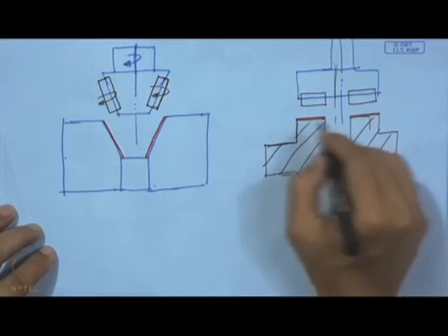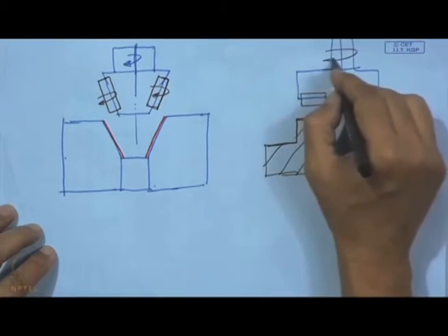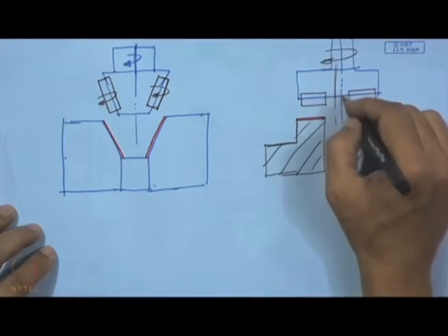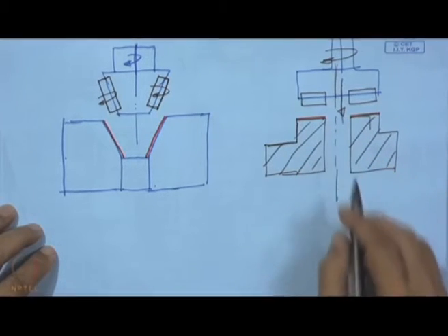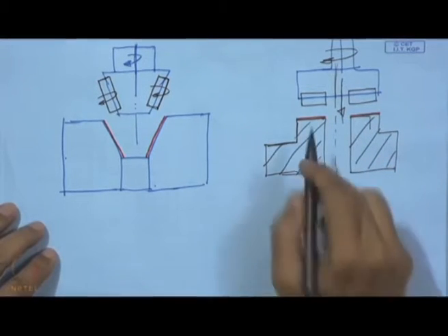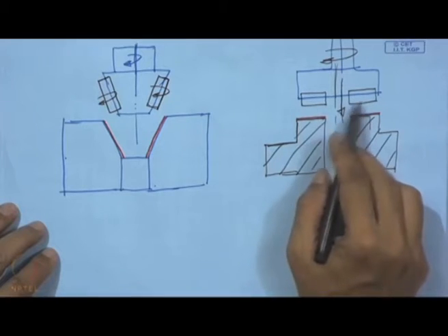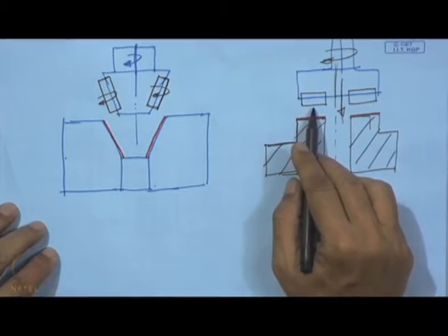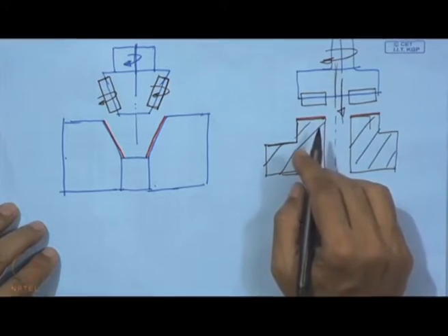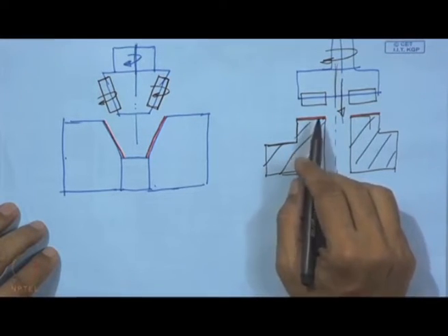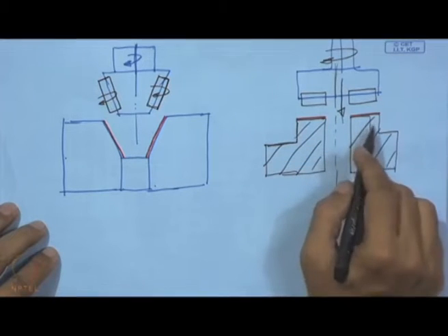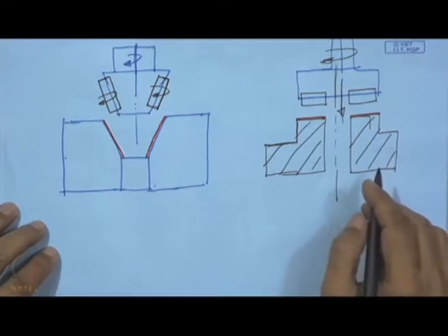It should cover these surfaces, and it will keep on spinning over this, and by pressing in this direction, these two surfaces immediately will be worked by this roll burnishing action, and in that case we can remarkably improve the surface property of this particular zone of this machined component.